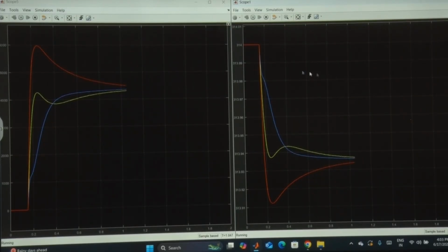The one which is giving more power, its frequency we are reducing more. Others have higher frequency. As the others have higher frequency, their relative angle, which is the integration of omega 2 minus omega 1 dt, increases. As the relative angle increases, the power starts to flow from these sources. Now these sources start to push power.